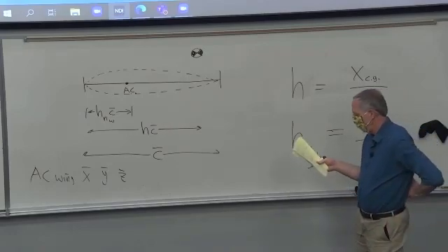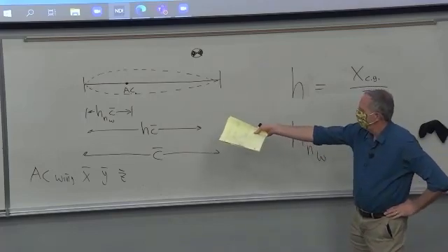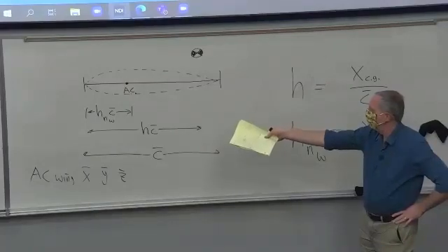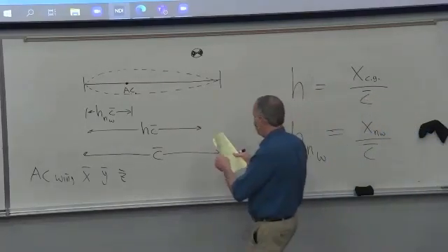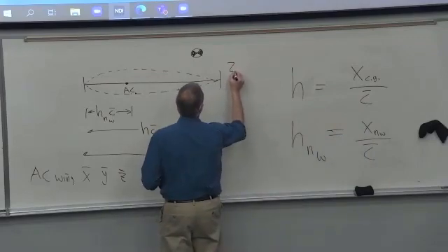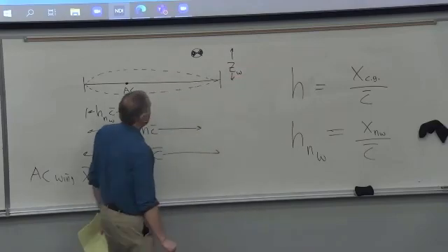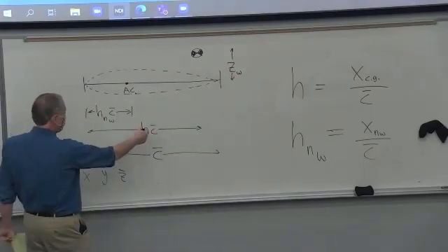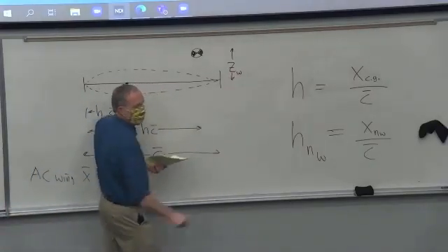So what have we done? We've done step 1, C bar. Step 2 is the neutral point or the aerodynamic center location. And then step 3 is defining where the CG is. Oh, and we need to keep track of this vertical distance as well. We'll call that Z. So the horizontal distance, I know it's weird, is H times C bar, but the vertical distance is just called Z.